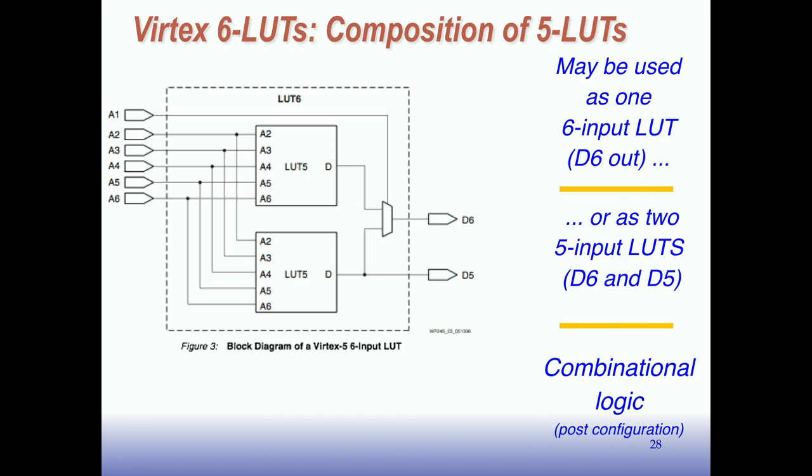And if you think about that, it's kind of like taking a 5-input truth table, another 5-input truth table, and then choosing between the 2 based on an extra input bit. So now we've made a 6-input truth table, effectively, with this idea. This is a general concept in how you make bigger LUTs out of smaller LUTs: you add one extra level of multiplexing here. There's multiplexers in here anyways, but you're just extending the multiplexer by one more layer and making this LUT twice as big.